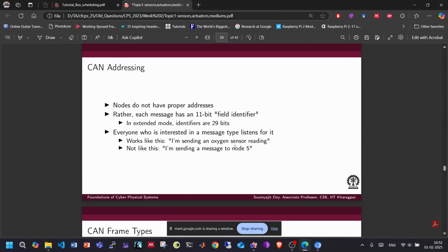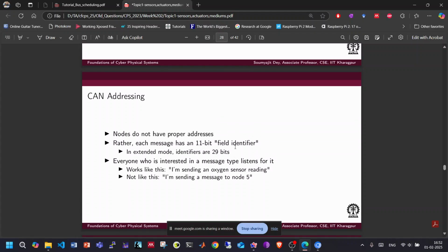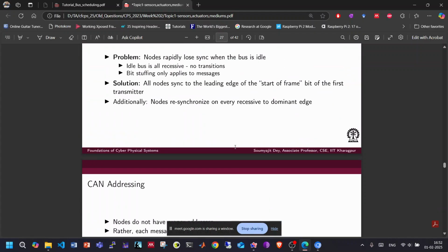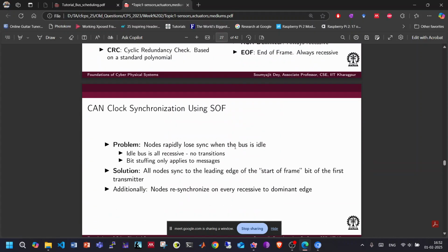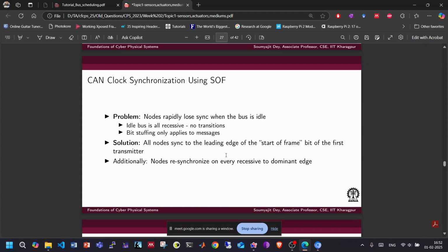Yes. Okay. So I am hoping you already understand what I was trying to say. When the bus is in recessive state, then we call the bus idle. Okay, in CAN, you have to sync after every 5 same signals, by toggling the signal. Yeah,